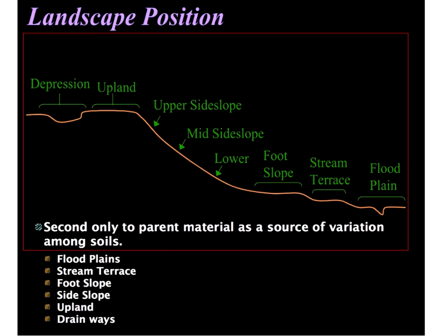Okay, and we looked at this yesterday. The landscape position is second only to the soil. In other words, if you have mediocre soil in a good landscape position, it might work pretty well, while mediocre soil in a poor landscape position might not be acceptable. So you have to look very carefully at the landscape position.